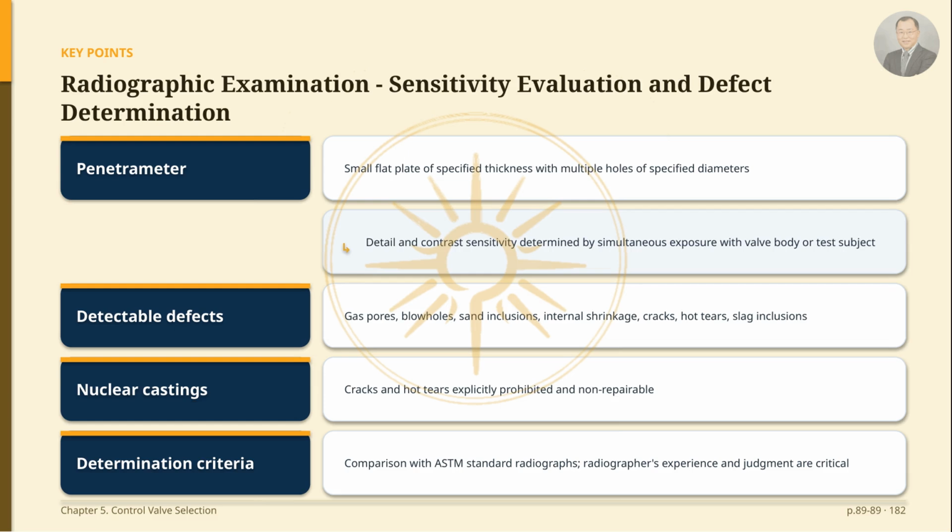Now, I will introduce the sensitivity evaluation and defect determination methods for radiographic examination in casting non-destructive testing. The detail and contrast sensitivity of a radiograph are verified by exposing a small flat plate of specified thickness, called a penetrameter, along with the test subject. This plate has several holes of specified diameters drilled into it. By observing its image on the film alongside the test subject, such as a valve body, the sensitivity of the